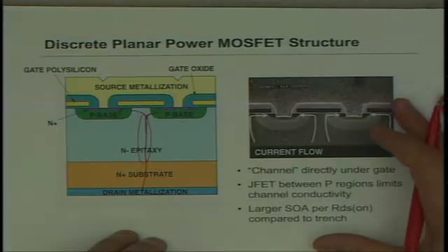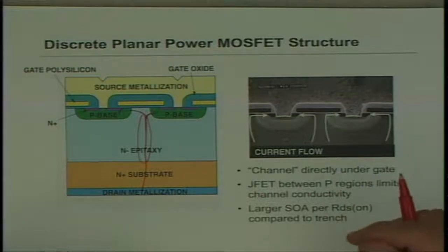The nice feature of these devices is they're spread out. The current flow or the current density is relatively low, so that they work well in the linear region. They can dissipate huge amounts of avalanche current or power, and so they're very stable operating under adverse conditions. They're considered very rugged devices. But the bad news is, because they're large and spread out, you need a lot of silicon acreage in order to get very high current.